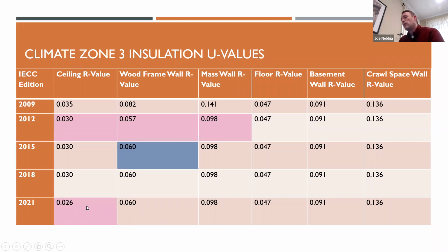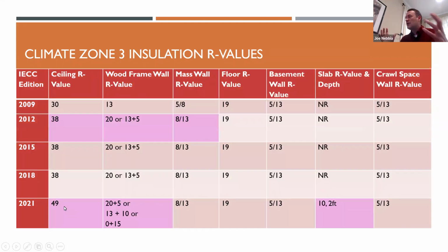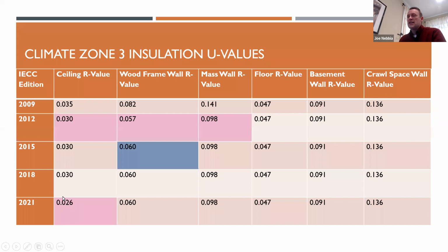This is also important when you look at that R49, because I know that's a little bit of a shock when the attic insulation changes. So pay attention to the U-factor, because that's what you're going to need if you do a whole building UA and want to trade off if it's difficult for you for some other part of the insulation or window in the building envelope.